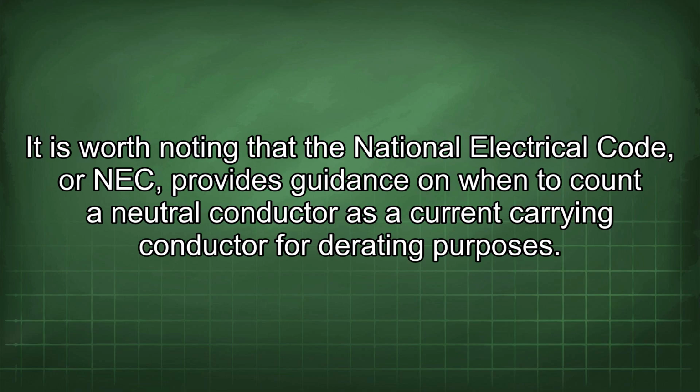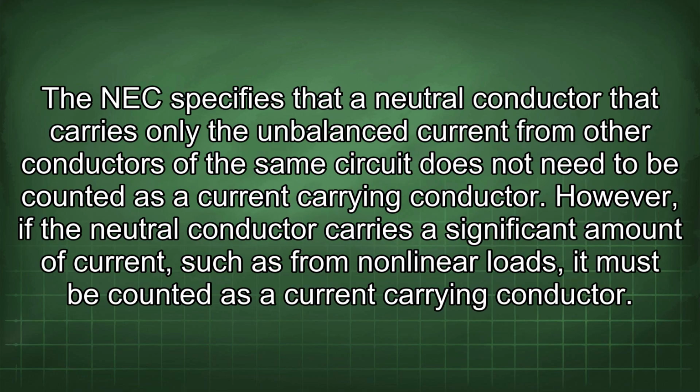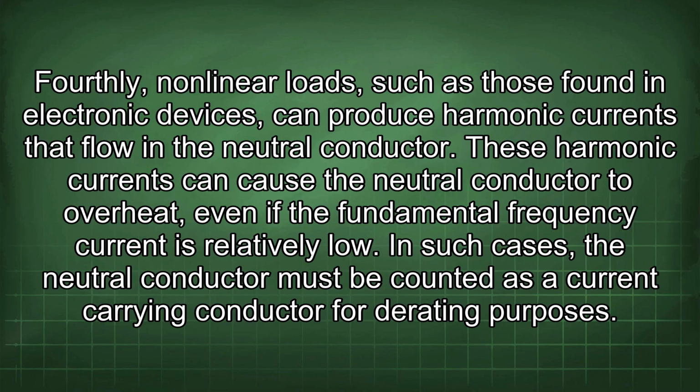It is worth noting that the National Electrical Code, or NEC, provides guidance on when to count a neutral conductor as a current-carrying conductor for derating purposes. The NEC specifies that a neutral conductor that carries only the unbalanced current from other conductors of the same circuit does not need to be counted as a current-carrying conductor. However, if the neutral conductor carries a significant amount of current, such as from nonlinear loads, it must be counted as a current-carrying conductor.